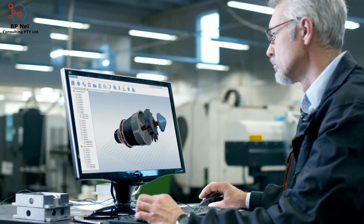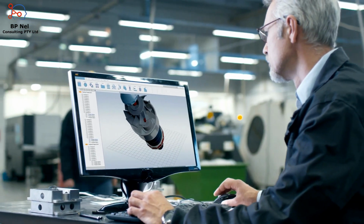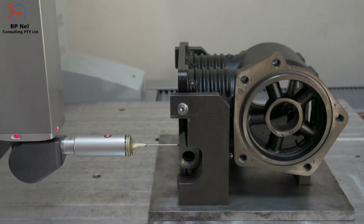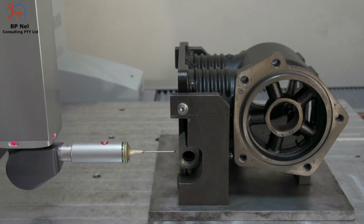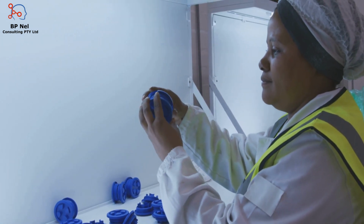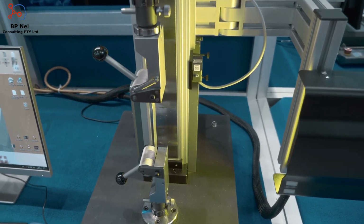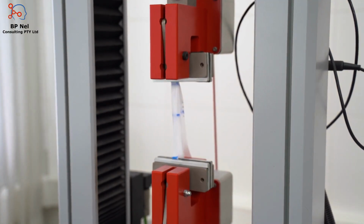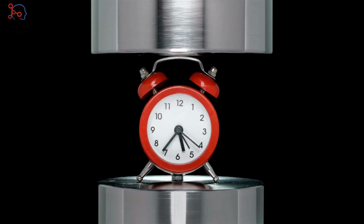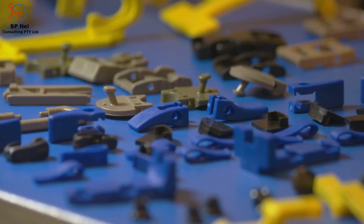Once you've selected the right material and perfected your design, it's time to put your plastic part to the test. Quality and durability aren't just buzzwords. They're proven through rigorous testing. Start with basic visual inspections to catch obvious flaws like warping or sink marks. Next, move on to mechanical tests. Tensile strength tests pull your part until it breaks, revealing how much force it can handle. Impact testing simulates drops and knocks, ensuring your part survives real-world mishaps.